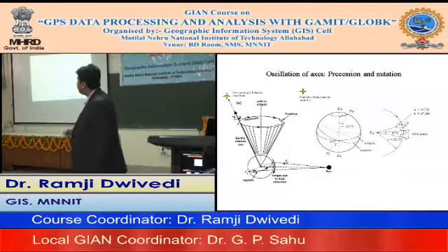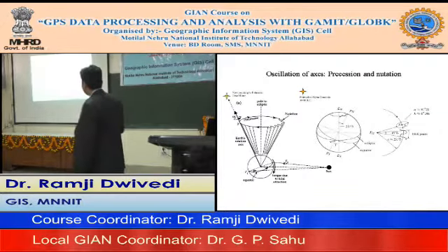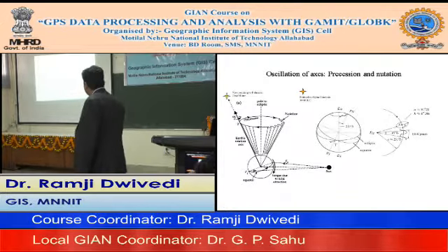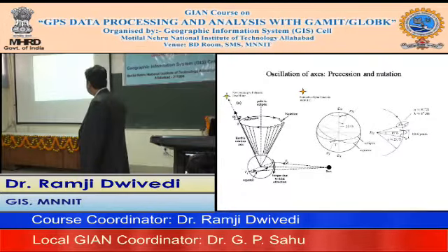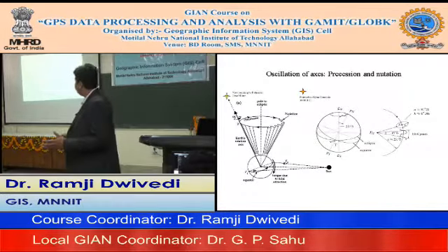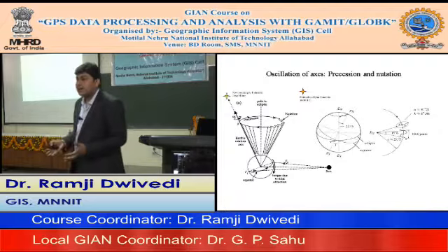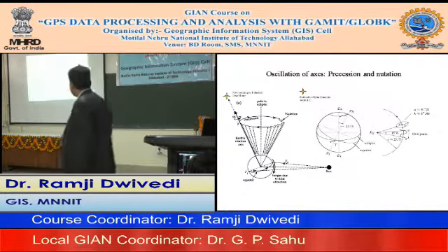It has two components: long periodic secular precession and short periodic nutation, with periods from 14 days up to 18.6 years. The period of this nutation is very short compared to the periodicity of the complete process, which we call secular precession. Because of this, we have to apply certain corrections when we move from a space fixed coordinate system to the Earth fixed system.